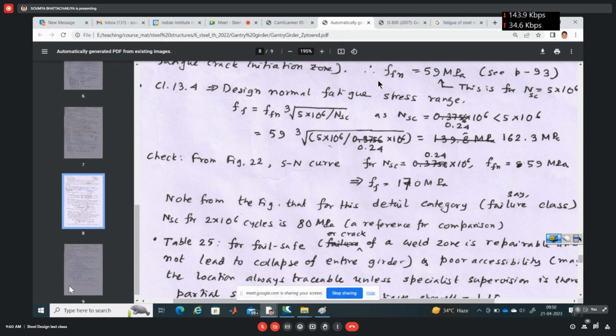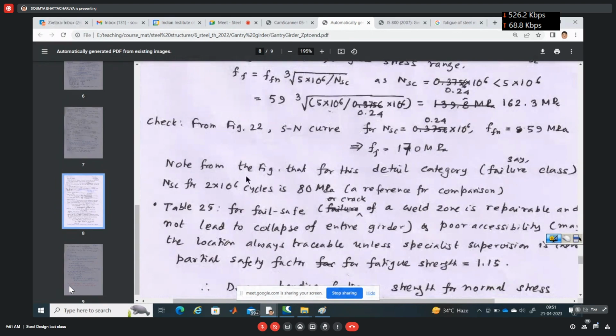The fatigue occurs because of stretching and then contracting gradually. At each time the cycle is passing, it is stretched, then gets released. Because of this stress cycle repetition, one time the material gets fatigued and it fails at much lesser strength than that expected.